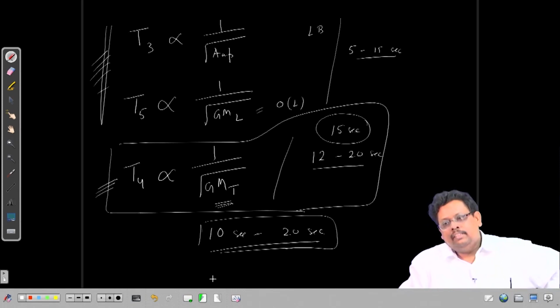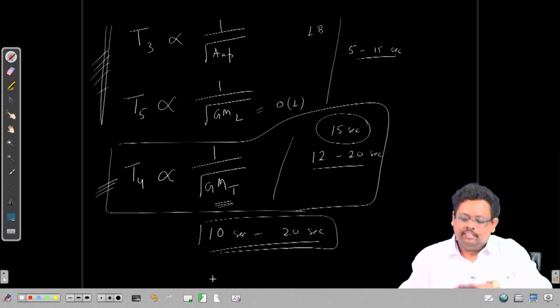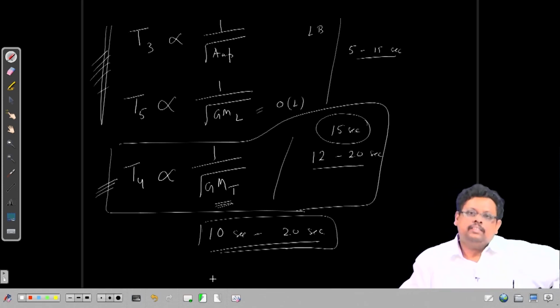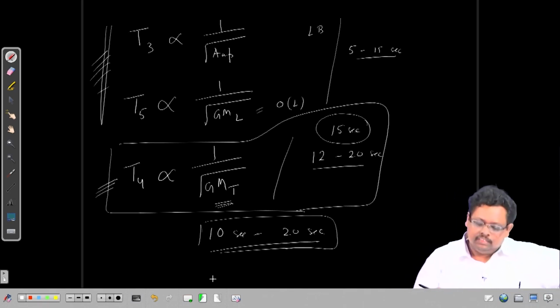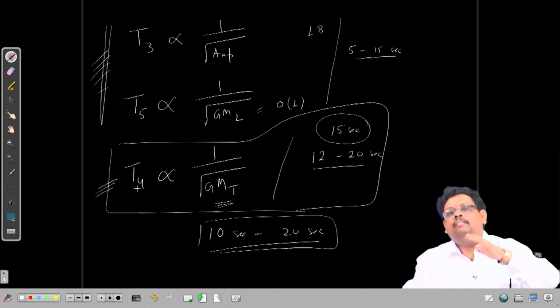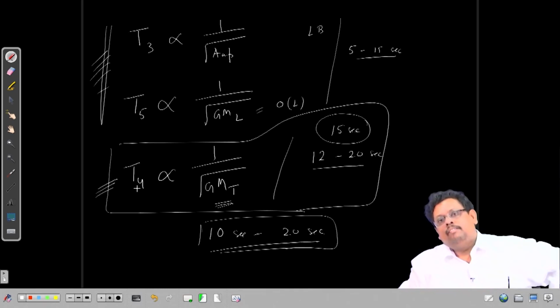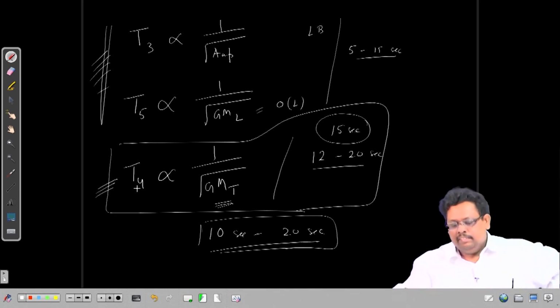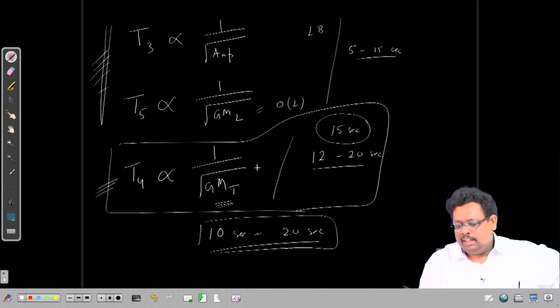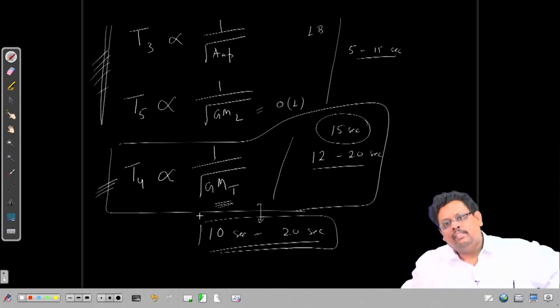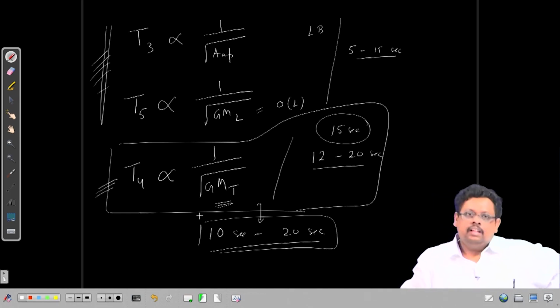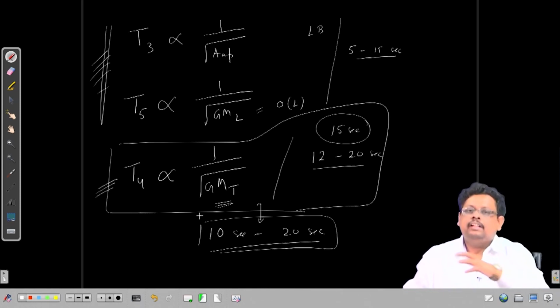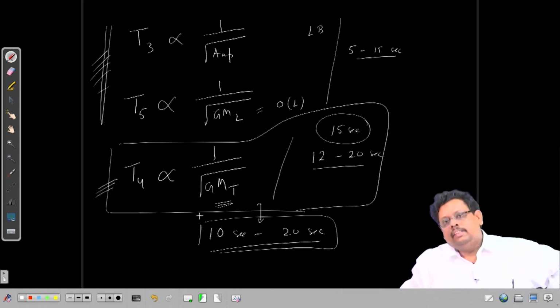Therefore, in the ocean we have to be very careful about the capsizing of the vessel, especially the roll. Also, because of this we have huge discomfort to the passengers, because if we start oscillating in a resonating mode, with waves hitting close to the natural time period of the roll, the passengers are in a very uncomfortable situation.